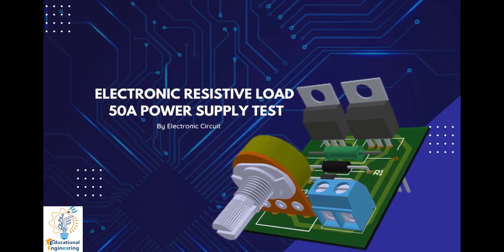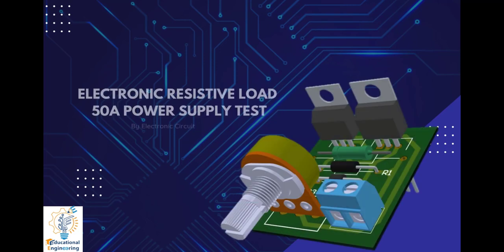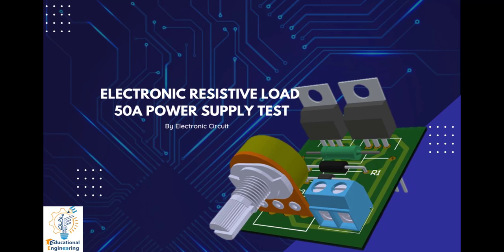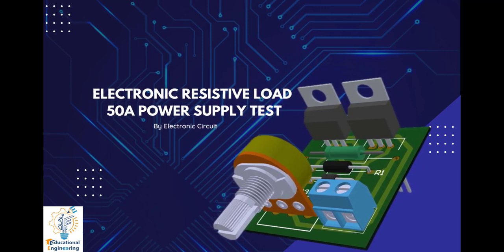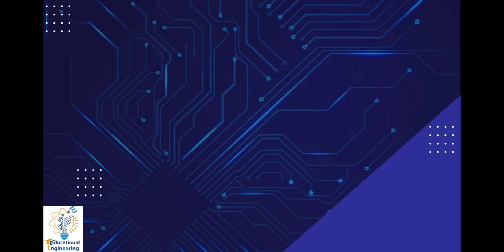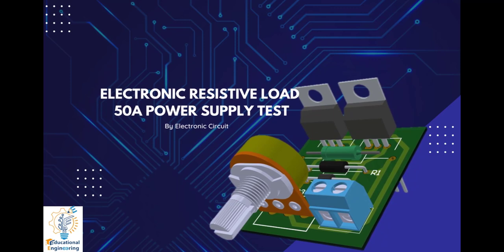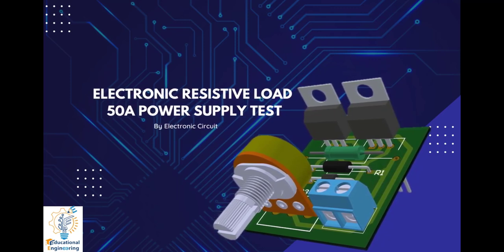Hi, and welcome again to another video. Today we're gonna learn how to design an electronic resistive load to 50 amp, originally made by Electronic Circuits. So this board is capable of withstanding an initial load for low voltage sources, 4 volts or 40 amps, and for voltage above 5 volts, current is 50 amp, supporting voltages up to 45 volts. So let's start designing it in Altium Designer.